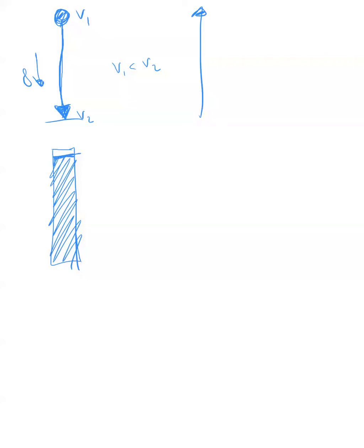And let's think about what happens with the pressure. If you read the lecture 20 material, then you know exactly what happens to the pressure. If I have gravity pointing down, then I have more pressure down here than up there. So P2 is more than P1. So if we forget about velocity and motion, the effect of gravity is that you have more pressure as you go lower.